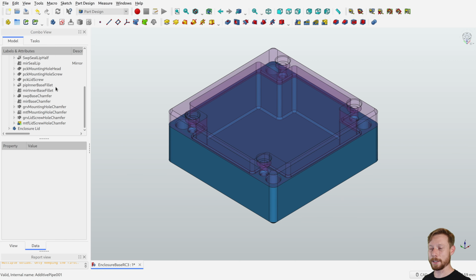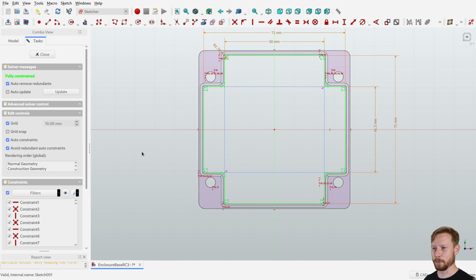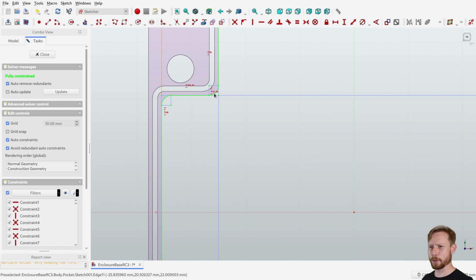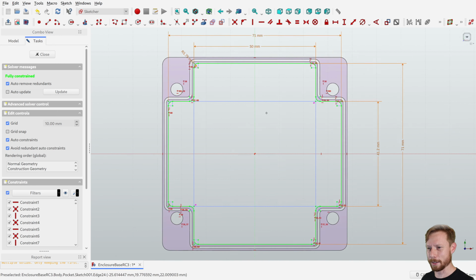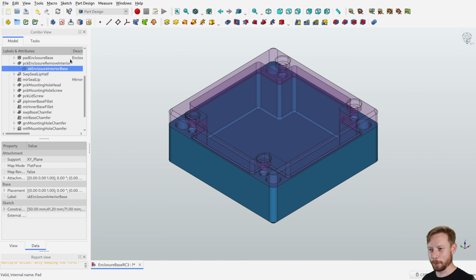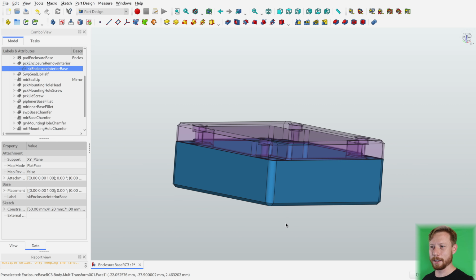But yeah, the easy one is anything that you pad or pocket. You can put your fillets in your sketch. You can put your chamfers in your sketch. This also alleviates a lot of FreeCAD's problems with fillets and sketches, because anything that you can draw in the sketch, you can pad or pocket. That doesn't solve the how do I put a chamfer on the top and bottom here. I can't put that in the sketch. Well, I model them manually. I use the additive and subtractive pipe tools to do so.